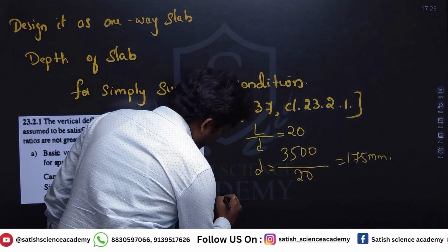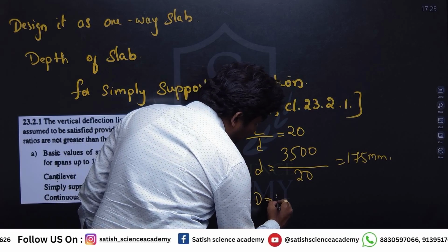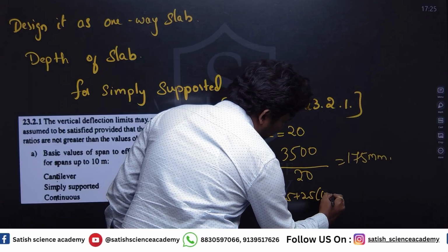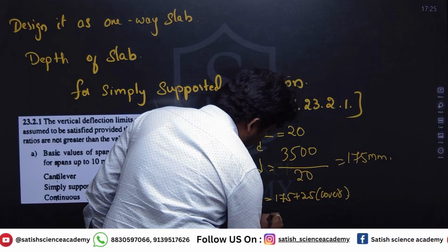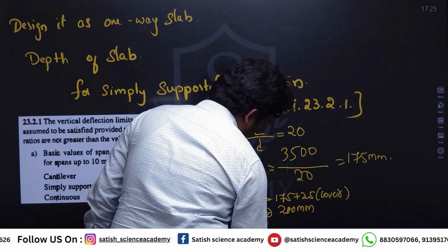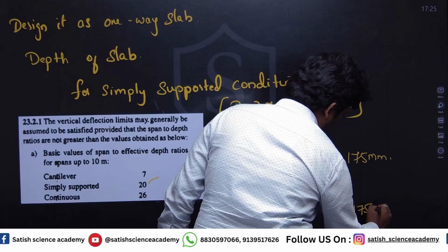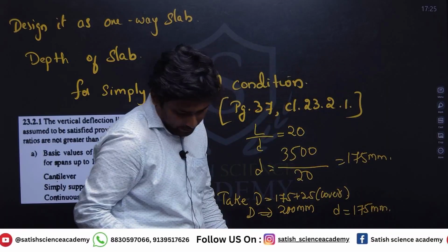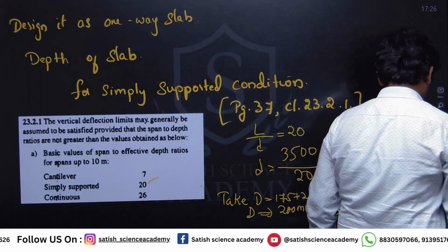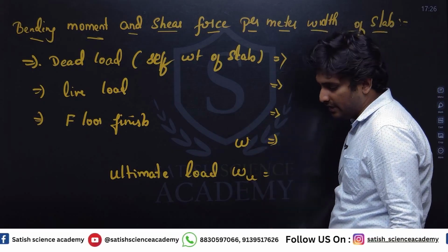Okay, now take capital D equal to 175 plus 25. This is cover. So this is 200 mm depth and effective depth d equal to 175 mm. Okay, so this part is understood. Now next will be the load calculation. Load calculation के लिए, that is bending moment and shear force के लिए required रहेगा.